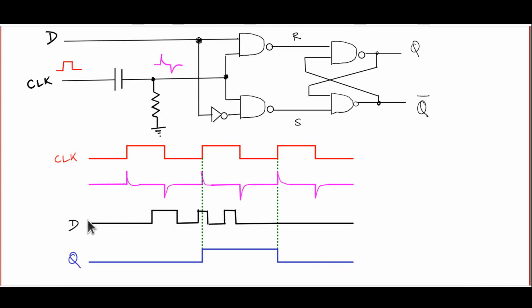So if you change the input of your D signal in this particular manner, this is just an arbitrary change that we have tried to illustrate. Note what will happen. Here the D has gone up. Remember, D and Q follow each other. Q becomes the same as D as long as clock is high. Now here, D is low and Q stays low throughout. D has gone high here. The actual clock signal is high, but what the circuit is getting is zero. As a result, Q doesn't change, does not respond to D, it stays zero.